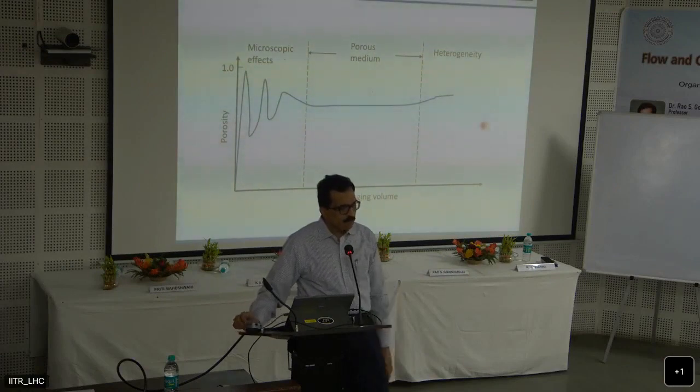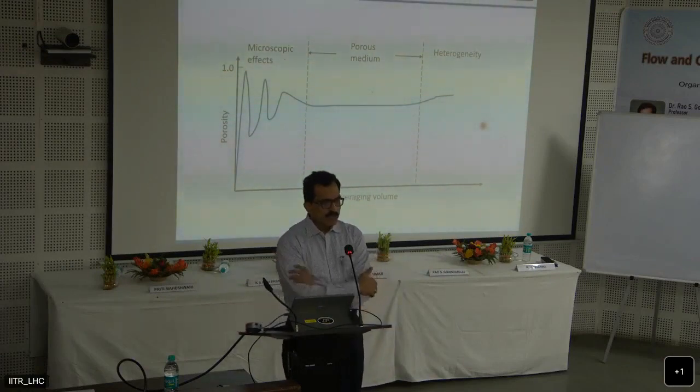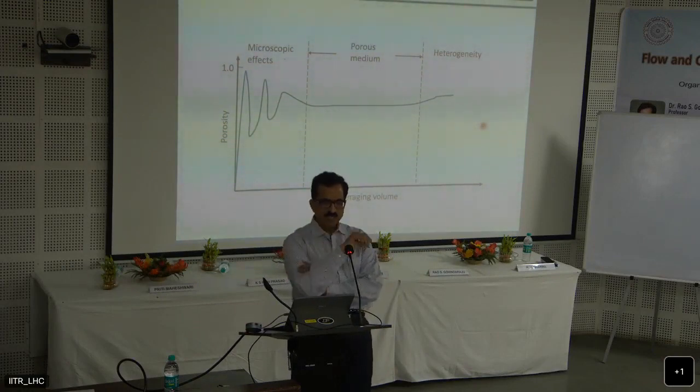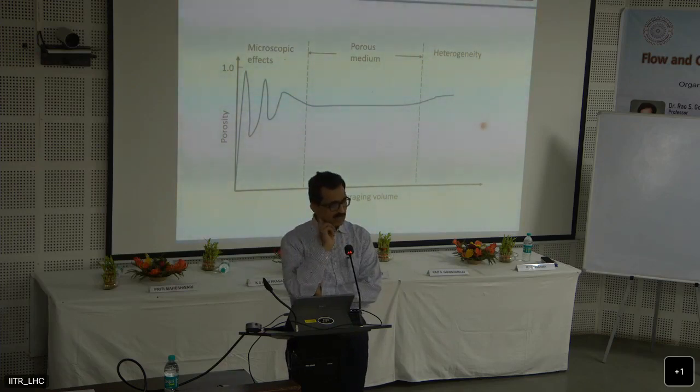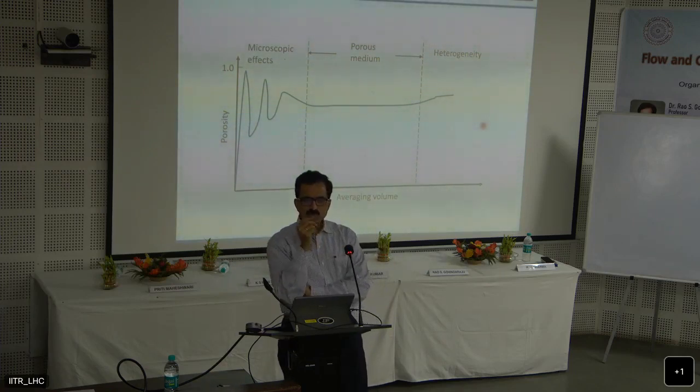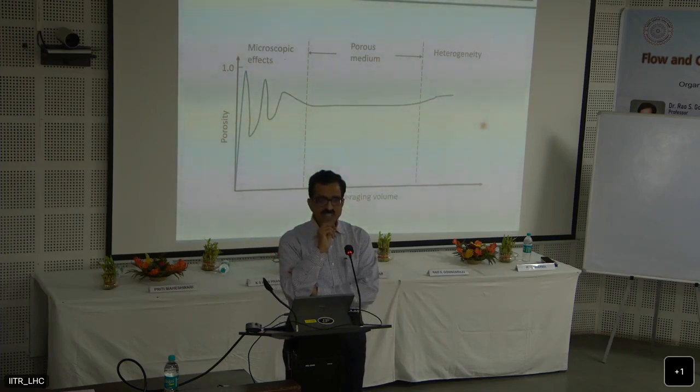If I'm going to do experiments with a conservative tracer that does not react with the porous medium, and we compute the Darcian flux and an experimental conservative tracer velocity, which will give me the effective velocity from which I can calculate the effective porosity, if those two are different, then I know that the effective porosity is different from the total porosity. I'm wondering if there is an easy way to do it only with flow. Do you know of a way to get an effective porosity experimentally, easily?